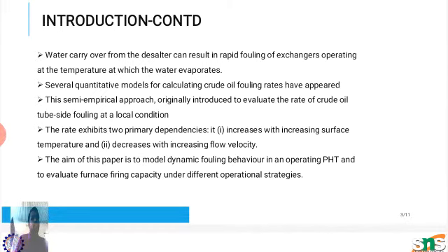In this manuscript, the hydraulic aspect of crude oil fouling is revisited. The crude is pumped via centrifugal pumps. These pumps are usually operated under constant rotational speed and are designed to maintain a target throughput even as the network pressure drop increases with fouling.